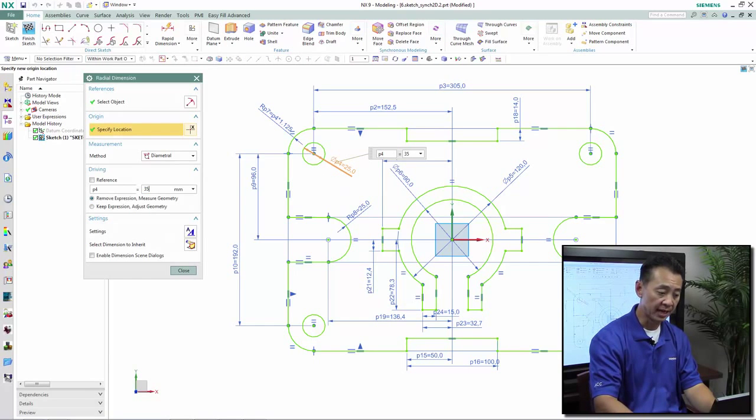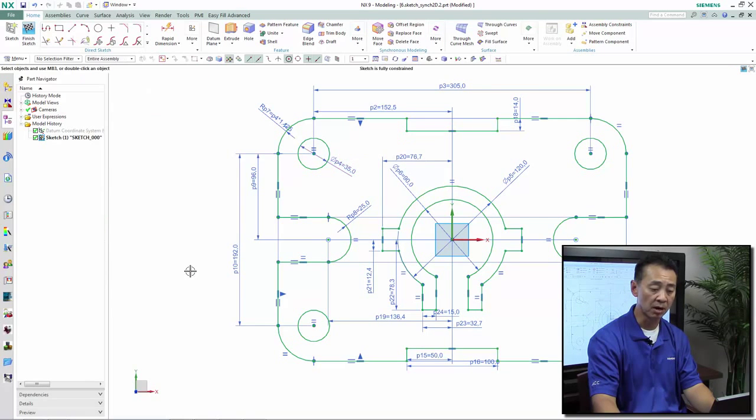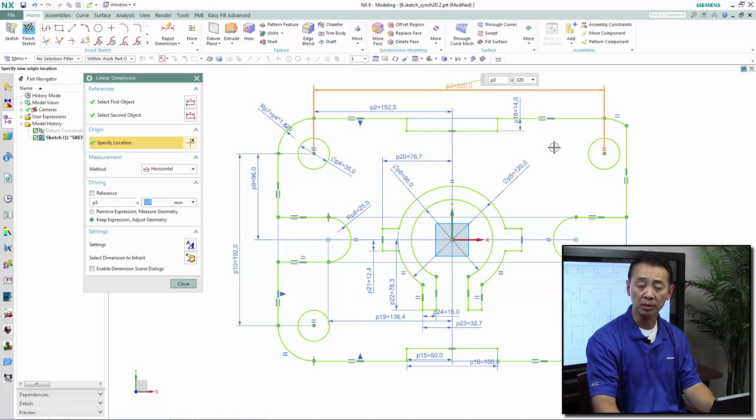Go ahead and change that to a different size, and I notice that all the parameters, all the dimension information has been updated properly. I want to go ahead and take a look at the other one. I want to change that value, and I notice that as I increase the horizontal length, not all the geometries update properly, which tells me that many of these geometry were not properly constrained. So therefore my design has failed.